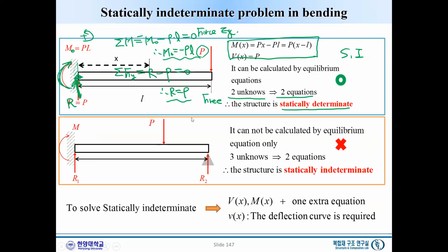And the reason, again, I want to emphasize statically determinate and indeterminate is that to calculate all the deflections, we have to be able to solve not only determinate but also indeterminate cases. So in the indeterminate case we have the clamp here, so we have a reaction moment M0 here, and a reaction vertical force R1 here.